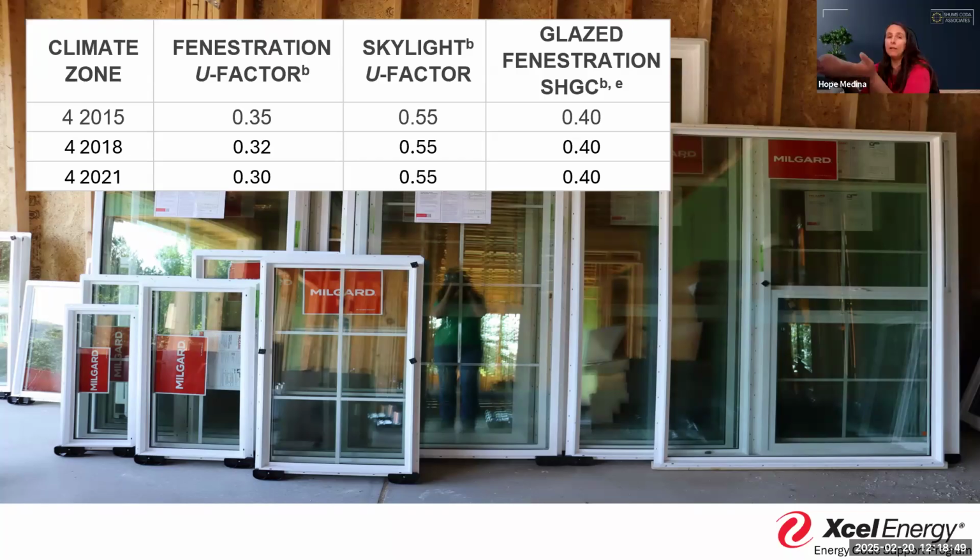So you're going to qualify it and say, hey, I got a 2x6 skylight and the U factor is 0.40. I'm just obviously throwing out numbers and so forth. But that's how you would incorporate that into the calculations for that heating and cooling load. Now, because you don't have that solar heat gain coefficient requirement with that, it may have more of a load to it than you might think.